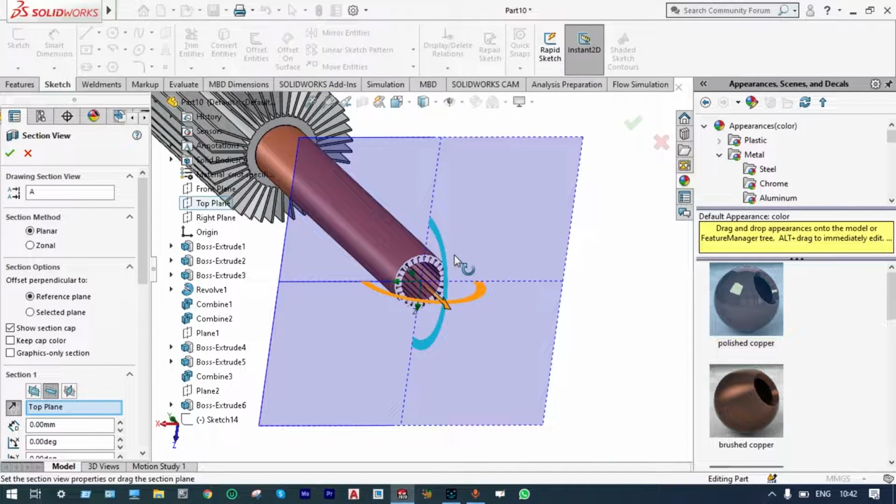So the heat pipe has specific advantages. That means its thermal conductivity is very high compared to normal copper, right? We can say that its effective thermal resistance is very low compared to normal copper. Through this analysis, we'll try to show its effectiveness, and also see the temperature difference at different cross-sectional areas or sections of the evaporator part, condenser part, and adiabatic part.